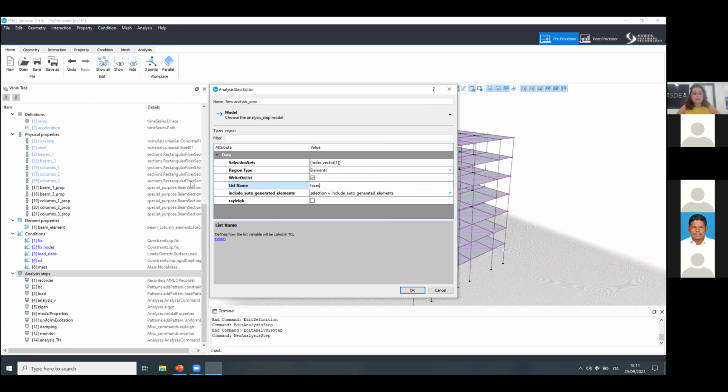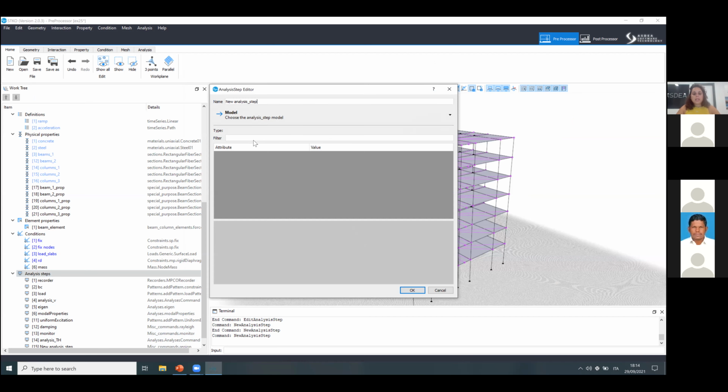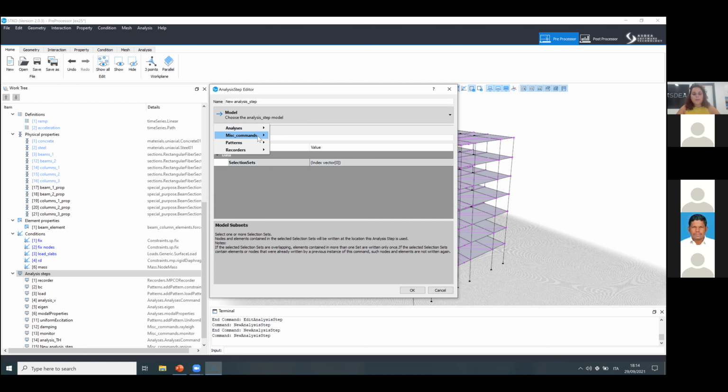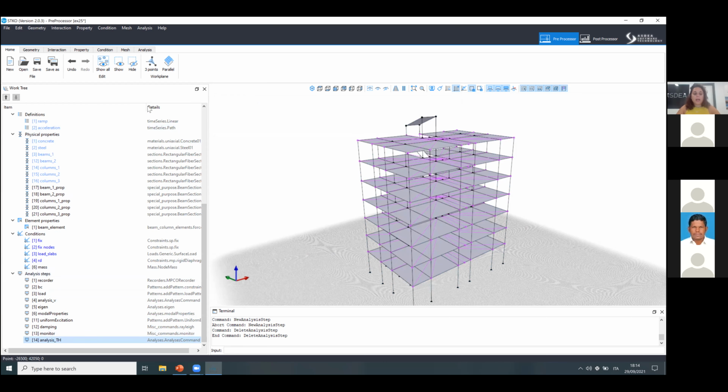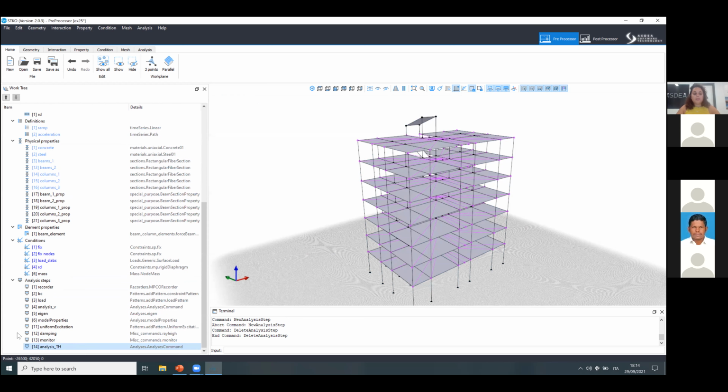And for some reason, you want to remove these elements from your structure, using a model subset, or in some way removing that element from your structure, then the damping will not be applied to that element. Or for example, if you're using constraints that are added afterwards, after the damping parameter is there, the damping will not be applied to that newly constrained structure.